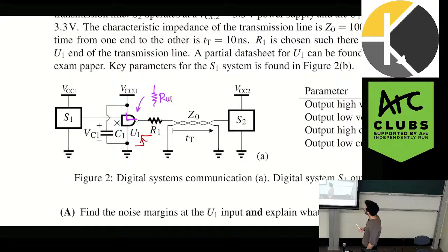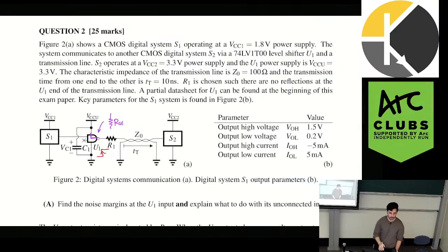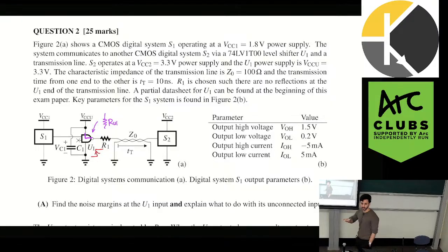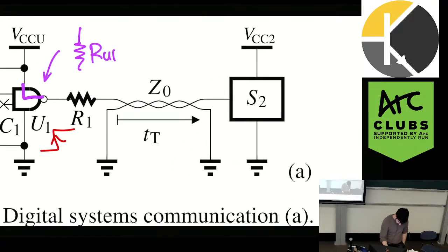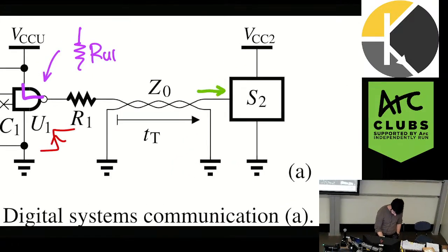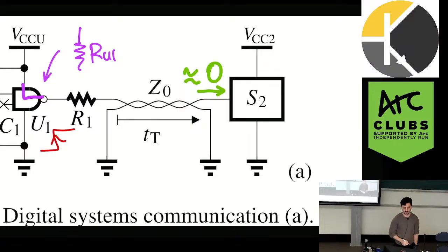Very small capacitance, so basically open. CMOS logic has hardly any current at the input, which is why CMOS logic is so good. So I know that the current going here is roughly 0. If the current is roughly 0, what does that mean the impedance seen there is? The resistance. Let's say the resistance.